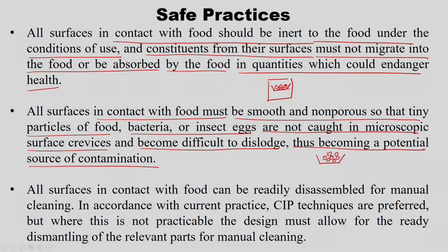All surfaces in contact with the food can be readily disassembled for manual cleaning. In accordance with current practice, CIP techniques are preferred with computer control, but this is not always practicable. The design must allow for ready dismantling of the relevant parts of the dryer for manual cleaning.